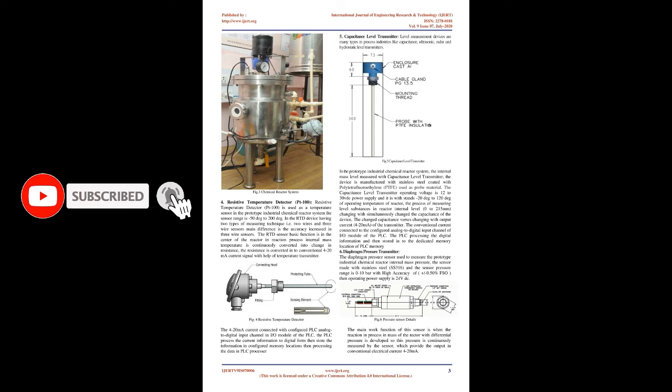3. Industrial chemical reactor. For the purpose of preparing bulk drug materials, a prototype industrial chemical reactor was designed. This reactor is made with stainless steel, SS304, and withstands temperatures above 300 deg. The internal mass maximum pressure of the reactor is up to 9 bar, and the isolated jacket pressure is 4 bar. The reactor system consists of a mass inlet and mass outlet, as well as a jacket inlet and jacket outlet, as shown